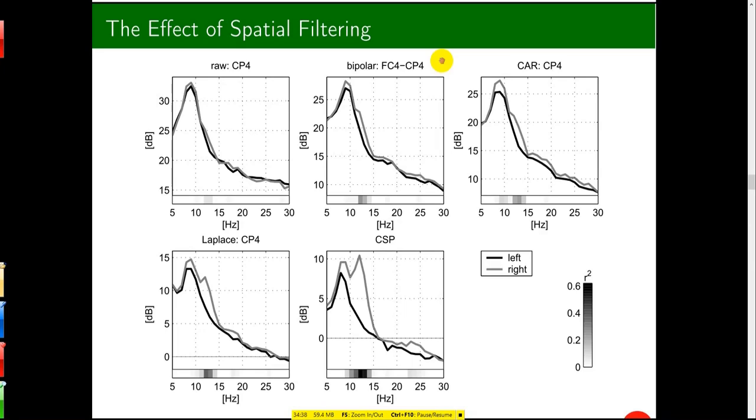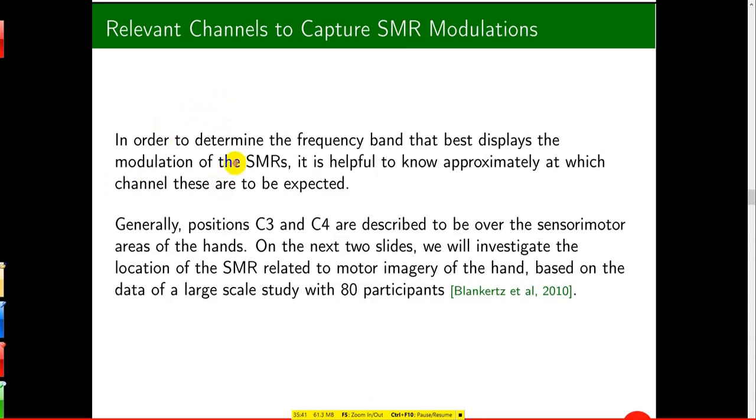Well, as I said, the current state of the art is common spatial patterns. It's a supervised learning method that tries to find optimal spatial filters that maximize the difference between two classes, and it has a very nice effect. You see, visually very separable, and the R-square metric also shows very separable patterns. Clear? So we know the problem, spatial smearing or the volume conduction effect, because each electrode picks up activities from different areas of the brain, and that gives us very overlapping patterns. However, we can improve that by applying not a temporal but a spatial filter.